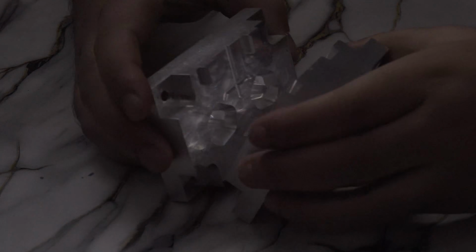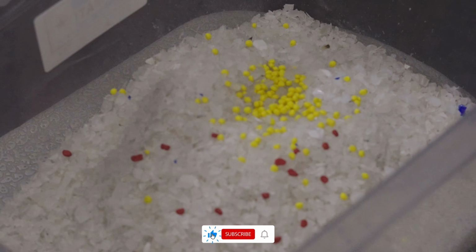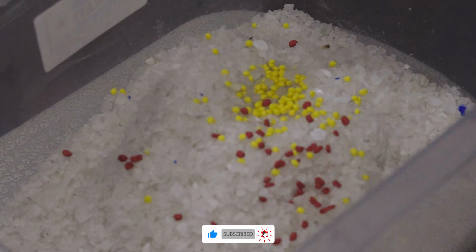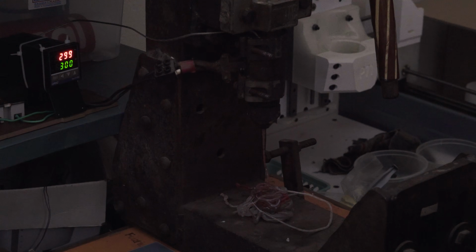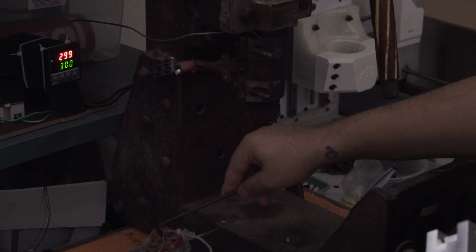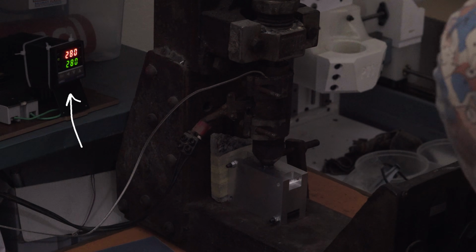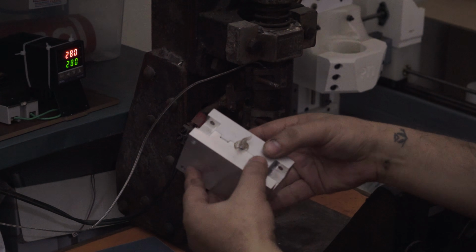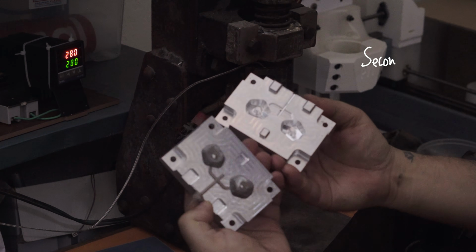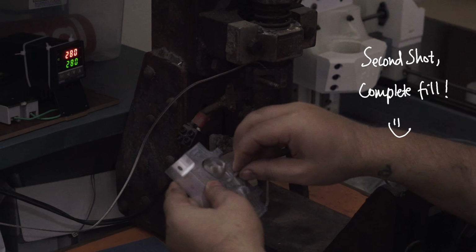Once the mold was machined, it was time to start molding parts. I'm using a small hand injection molding machine that can mold around 15 grams of polypropylene per shot. I also connected this REX-C100 digital temperature controller for temperature regulation so the plastic melts consistently. Then I started molding the beads.